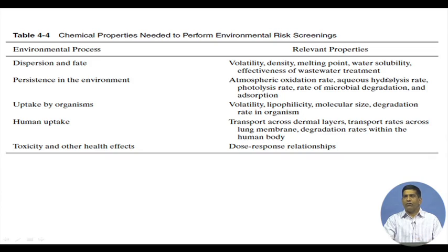See, most of the wastewater treatment plants we have in the world today are designed to treat for organics. Since we have higher organics coming from the fecal matter, they are essentially a set of aerobic and anaerobic systems where we are focusing on removal of BOD, biological oxygen demand, which is essentially coming from organic load, and ammonia. So we have nitrification, denitrification, and all those things happening. Some are doing phosphorus removal, nutrient removal, and all that. But if you look at the way chemicals are being produced today, most wastewater treatment plants are not designed to treat for those chemicals.